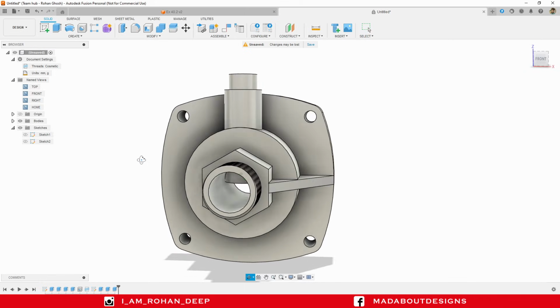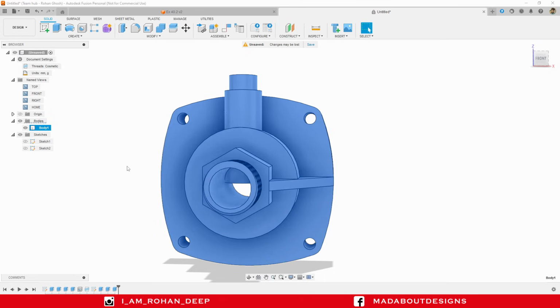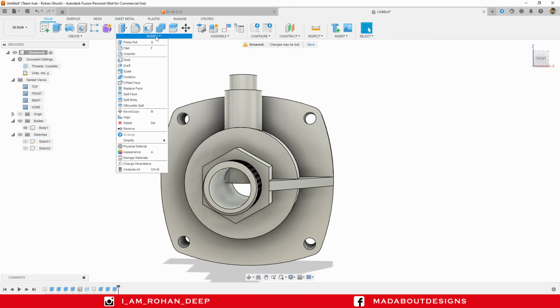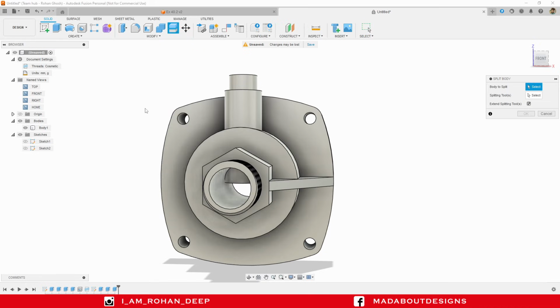Now you can see we have got an extra body here. We need to remove it. But before that, you can see all the bodies are joined together. So I need to separate this part from the whole body. To do so, under Modify, click on Split Body.